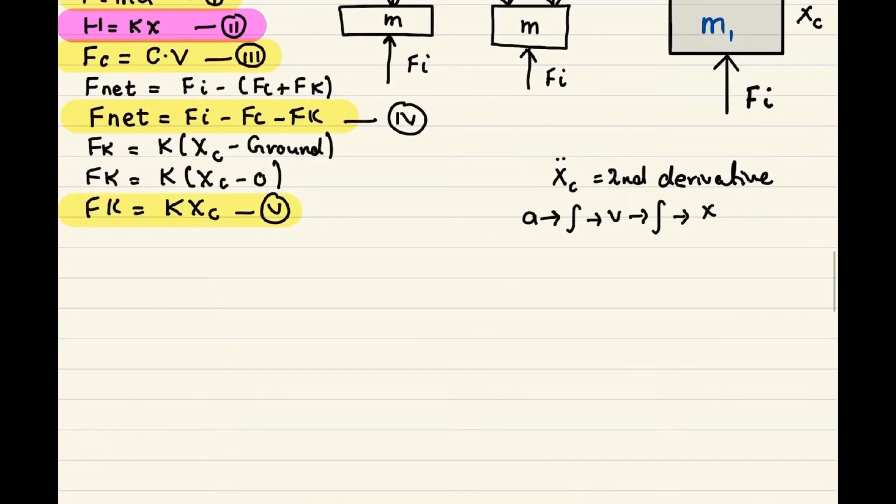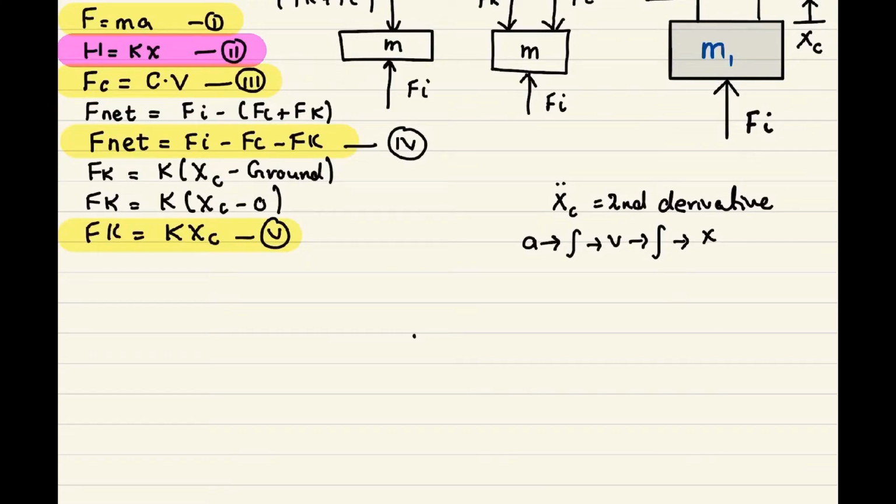So to draw the block diagram, we start from the integral part, and let's say this is the first integral. When we enter the acceleration we'll get the velocity, and when you again integrate the velocity you will get a displacement, and let's give this the same variable name as in our question, xc. Now we've got a entering into the integral part.